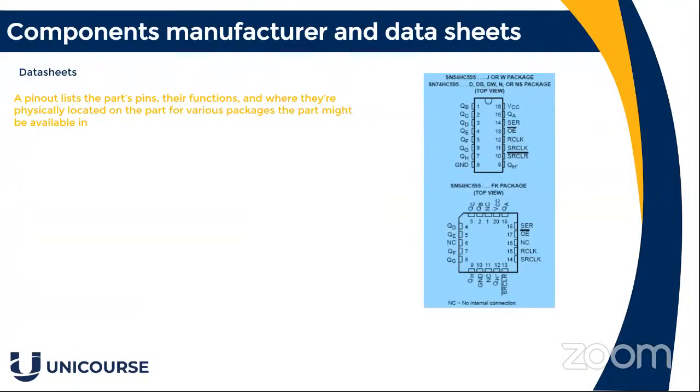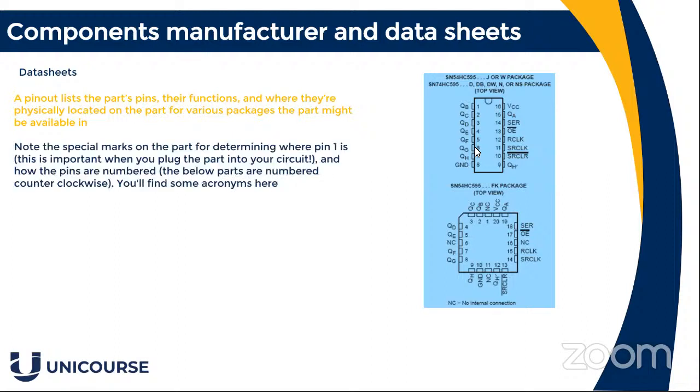So here we have one data sheet. Now this one here will give you, for an IC, the pin layout. Now for this assignment, you'll only need to do it for one, which is the operational amplifier side of it, which is an 8-pin dual in line. But sometimes you are looking for more complex ones, depending on the supply voltage.